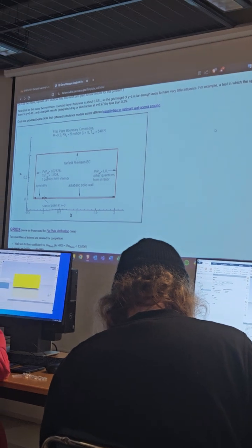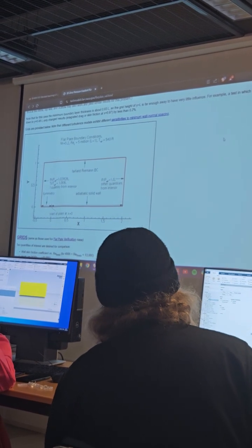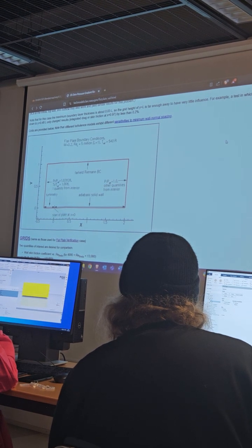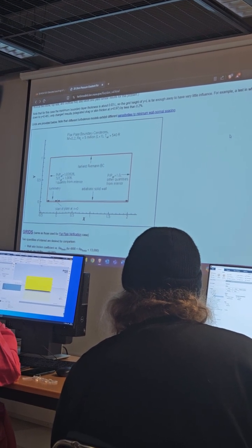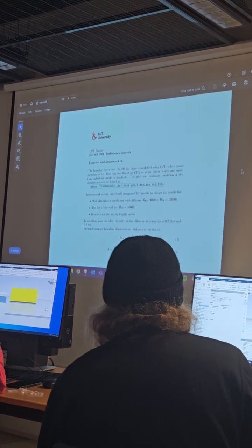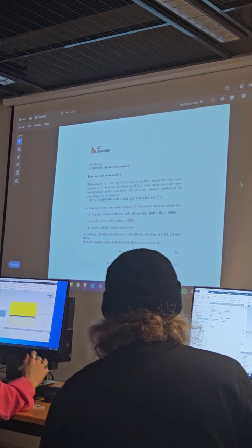You can actually load that in Fluent. You can actually import it or read it in Fluent, and you just need to change the turbulence model. Right now, I'm showing you how to set up the case from scratch again, but it's basically straightforward. If you have that ready, then you just need to change the turbulence model to a one equation turbulence model.